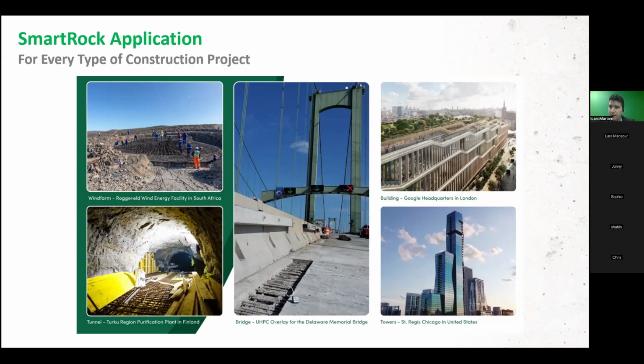But more than that, following ACI 207, they need to respect temperature differentials. Because the sensor measures body and cable, you can calculate the difference of temperature between one and the other. And that is in my next slide coming up, Hugh.